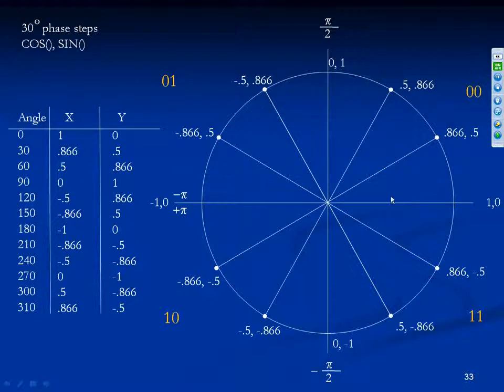So here's the table. This is our quadrant 0, 0. In other words, the most significant two bits of that phase accumulator are 0. And here the most significant two bits are 0, 1. I got these backwards here. They're supposed to be plus. I got those switched, sorry.